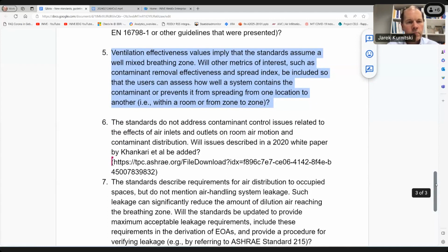We believe it's important, but it was also one of the most difficult things we could deal with, because some of our concepts of ventilation effectiveness don't work when you put air cleaners into space. For example, displacement may be better for indoor air quality generally, but if you're using upper room germicidal UV, a well-mixed space actually increases the performance of the UV system.